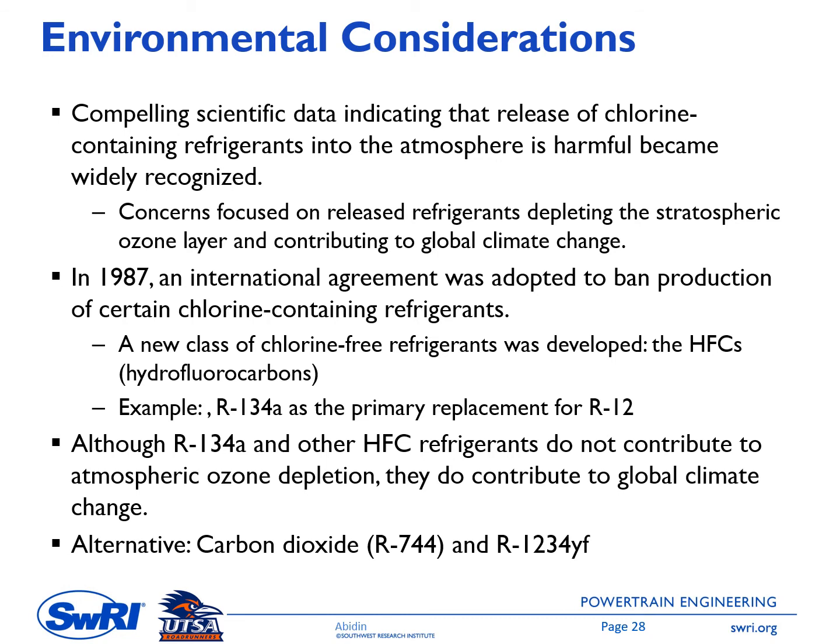This is the HFC, hydrofluorocarbon, which means there is no Cl there. Under this HFC type refrigerant, we have R134a as the primary replacement for R12. Once again, R134a is an allowed refrigerant. However, it costs more money. Although R134a and other HFC refrigerants do not contribute to atmospheric ozone depletion, they do contribute to global climate change. And then we have another type of refrigerant here, CO2.